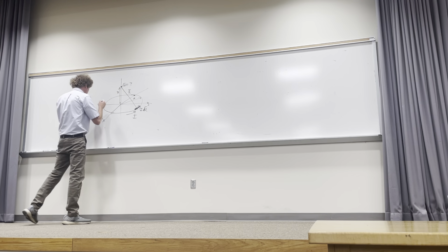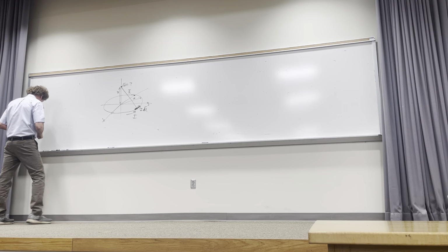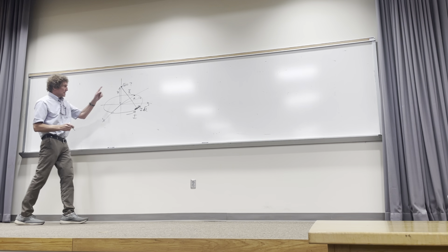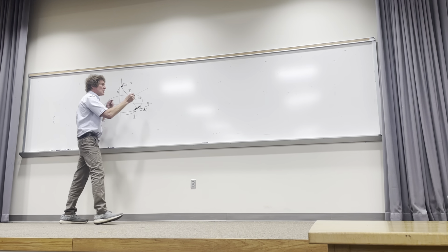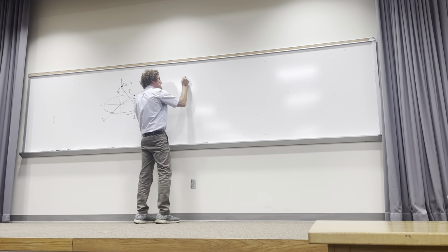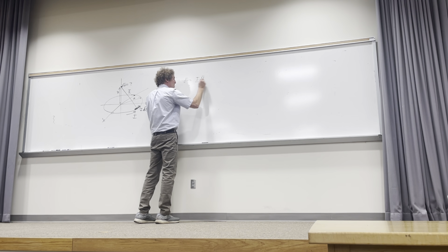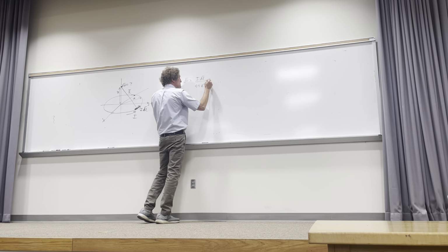I need to find the differential H field up there at this point. And again, the general form is dH is equal to I dl over 4 pi R squared, and it's going to be crossed into aR.